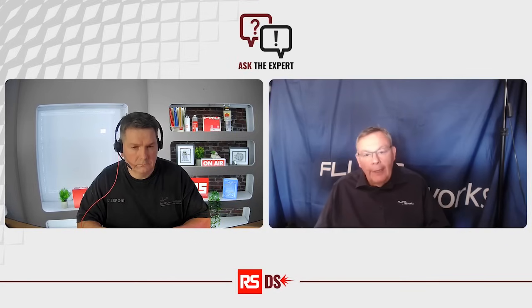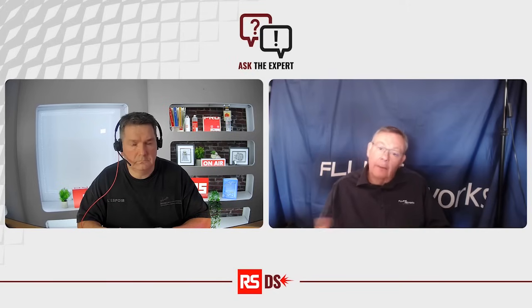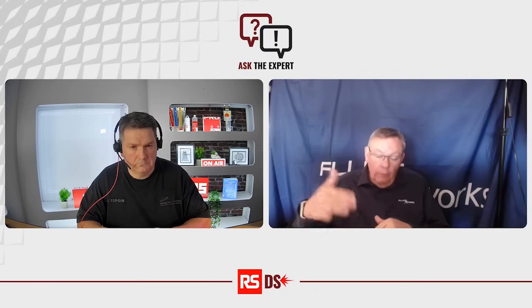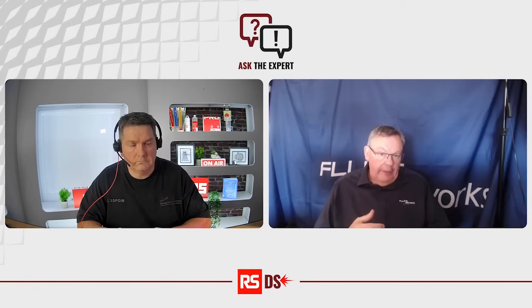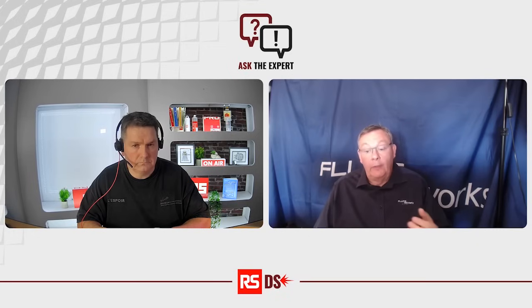And that is covered by, in TIA terms, the category 6A installation cable and installation standard, or in ISO terms, the class EA. They're basically equivalent to one another. And then we step downwards from there. And it really depends what the application requires. The application requirement will be dependent on the hardware that's being used. So different devices will have different requirements. And we may choose to change the cable type to match the device.